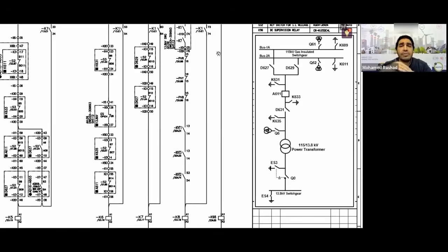What does it mean to have no voltage difference? It means the voltage before the disconnector and after the disconnector must be synchronized. You might say, great, I can do it like a circuit breaker, check synchronization and close the disconnector. I'll tell you that's wrong.